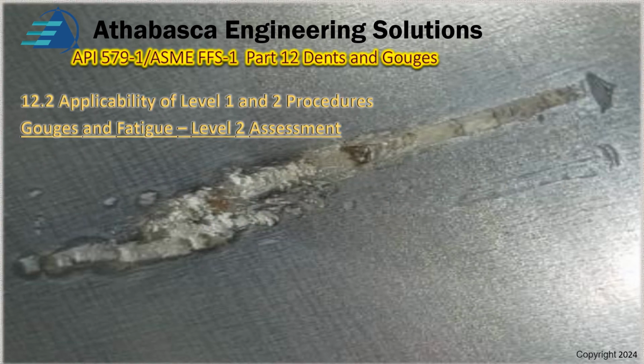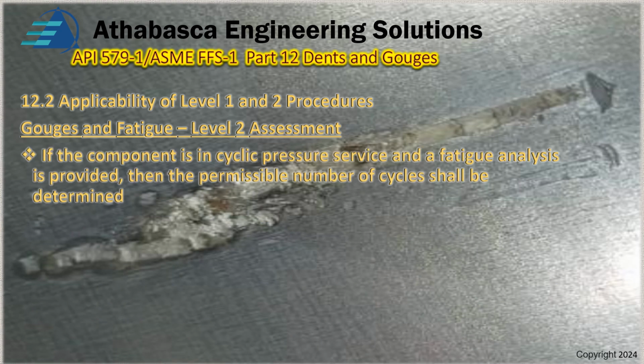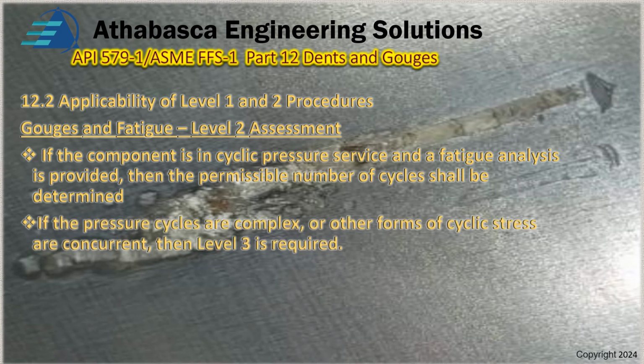For level 2, there are a few conditions. If the component is in cyclic service and the fatigue analysis is provided, then a permissible number of cycles shall be determined. Second, if the pressure cycles are complex or other forms of cyclical stress are concurrent, then a level 3 assessment is required.